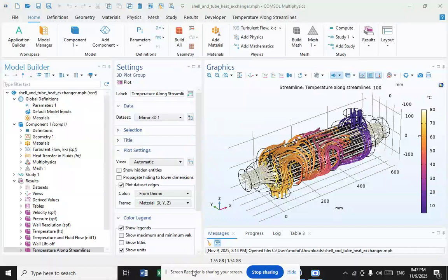And what about the waste heat recovery units? A waste heat recovery unit or WHRU is a heat exchanger that recovers heat from a hot gas stream by transferring it to a working medium, typically water or oils. The hot gas stream can be exhaust gas from a gas turbine or a diesel engine, or waste gas from industry or refinery.